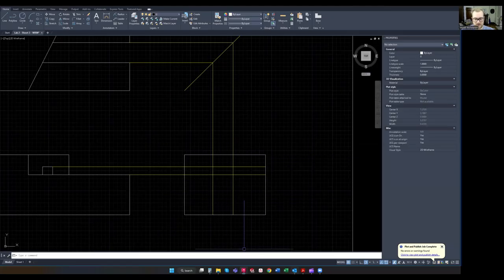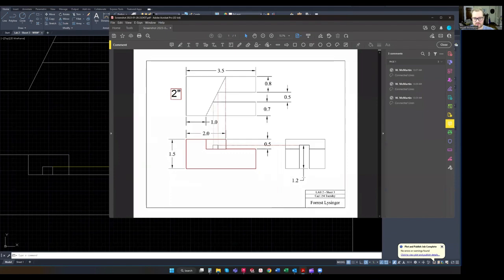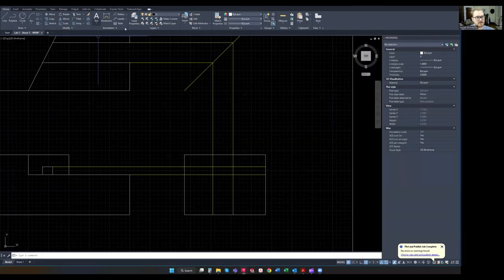Then if we look at our part here, we see this 1.2, it goes past these two lines, and we trim out right here. So we just trim everything all the way up to this line up here. So let's do that now. I'm going to use my trim tool, just like that.